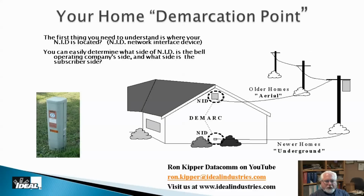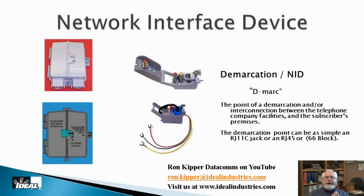Okay? Now, that phone line is going to be coming to the home or apartment or wherever it is, either aerially or underground to the outside of the building. A lot of new construction is obviously underground for safety reasons. Usually it comes out of one of these little green-looking pedestals that you'll see out there, and it terminates to the side of the building at what we call a demarcation point. Now, 40 plus years ago, this was a porcelain terminal shoved up underneath the eave of a house. Today, it's always going to be a gray-looking box, and we call it a network interface device. If you hear the phone boys ever talking about their NID, that's what they're referring to.